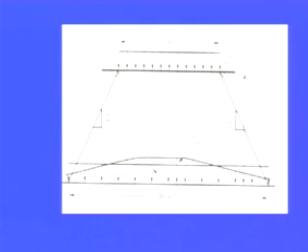If we want to determine the stress increase due to this at a level Z, depth below the ground surface, we have to consider this 2 vertical to 1 horizontal load distribution, and then the loaded area at that particular depth becomes equal to the width B plus Z, and hence we can determine the increase in stress as B into q into the dimension in the other direction.